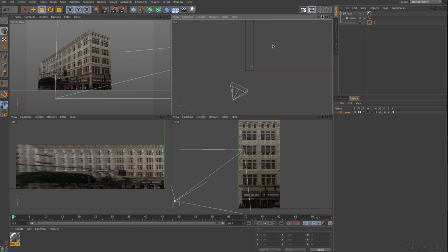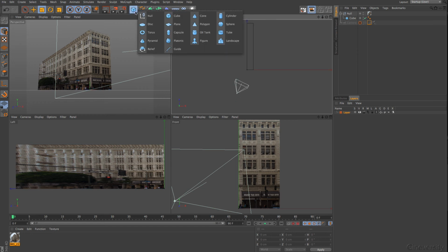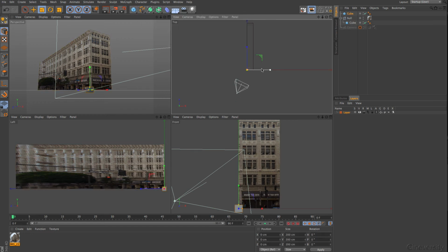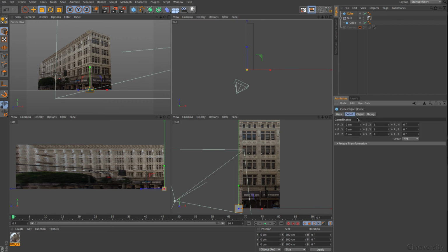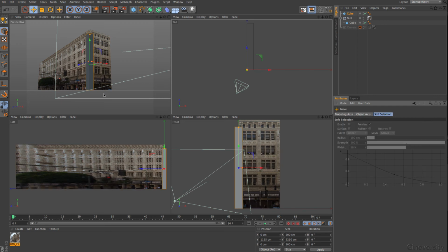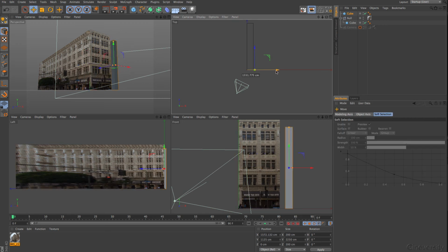That means we go here now, drag another cube into the scene. Now I know where all of that is. I can go here to attributes, to objects, and to 2250. Maybe the other building is higher, but this gives me a nice height from the start. This would be 1125 to have it pretty much on the floor. I assume that the floor is exactly in this way.